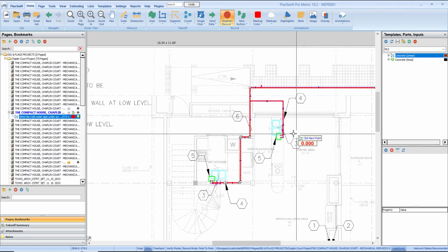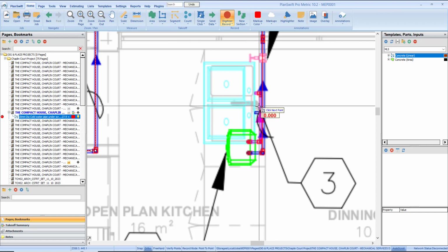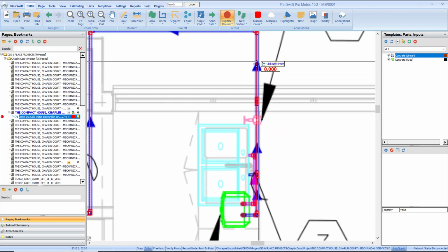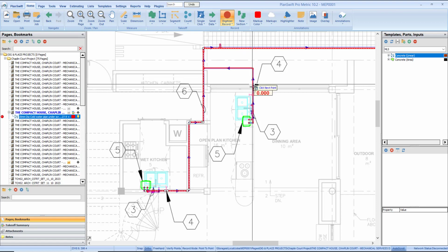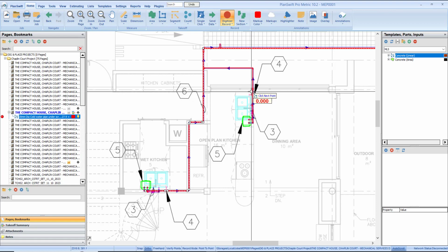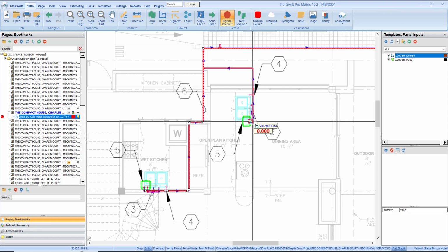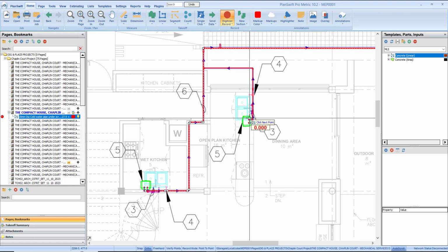So at this point you can see that we have over measured that of our 20 cold water supply that is under the screed. So we are supposed to terminate it somewhere around here, and then the others are going to be for the 20 which is in the wall. But I don't want to really separate that because they are the same diameter.